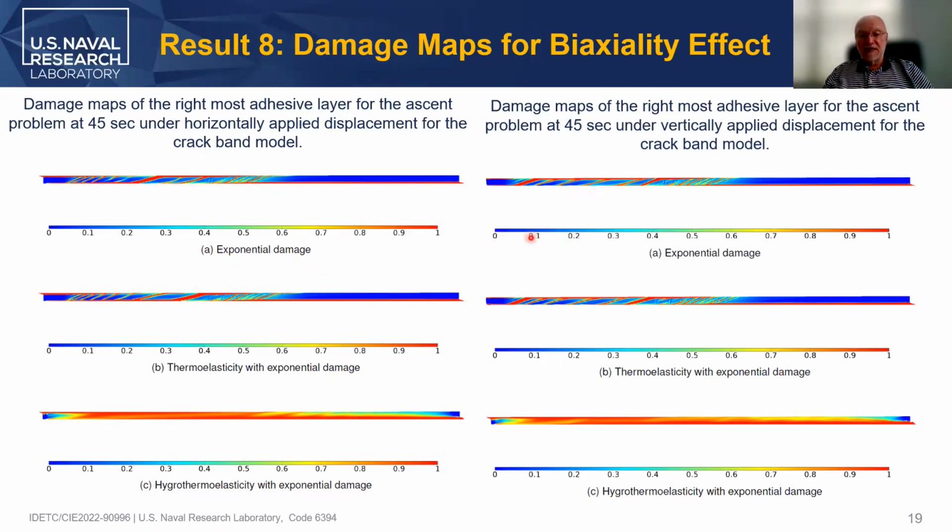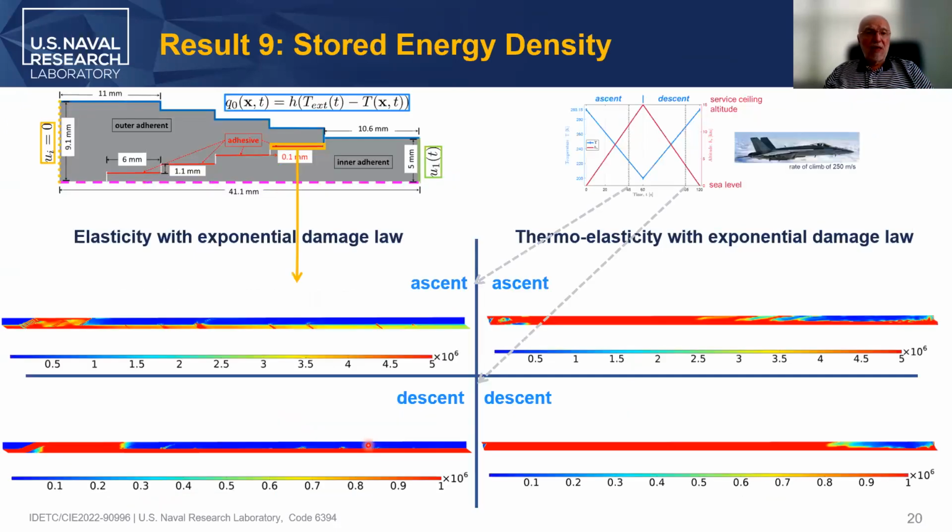And you can see the difference left to right in terms of the loading. There are differences. They're not really very drastic, but there are consequences of the fact that the load redistribution is different because of the boundary conditions being different on the side of mechanics, while on the side of thermal and hygrothermal effects, they are the same. But yet, the condition that contains all the physics is really the most critical one, as you can see on the bottom two graphs for both load modes.